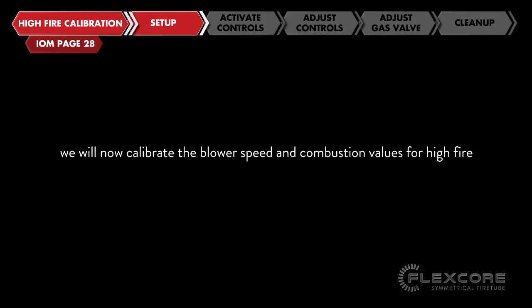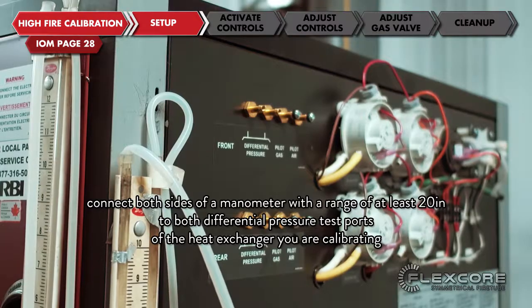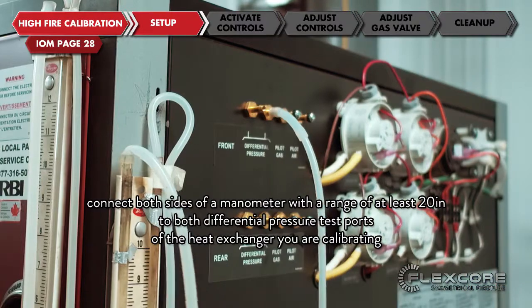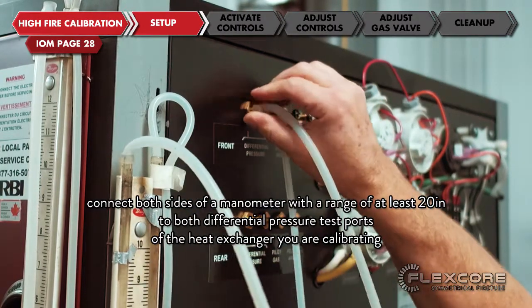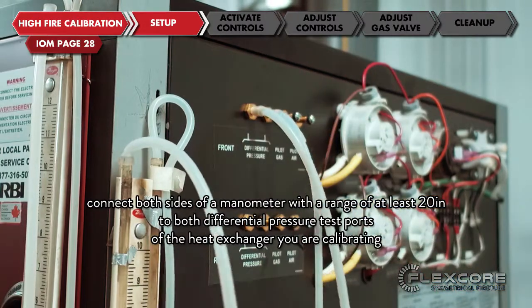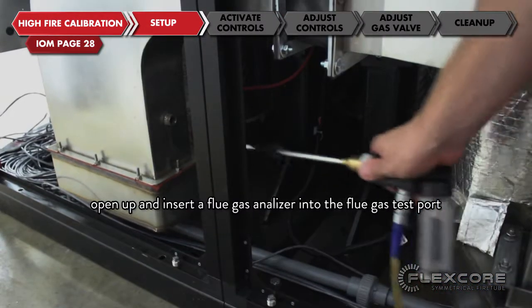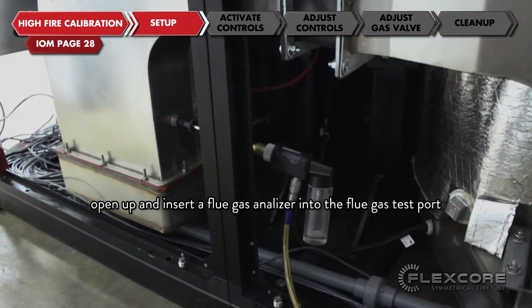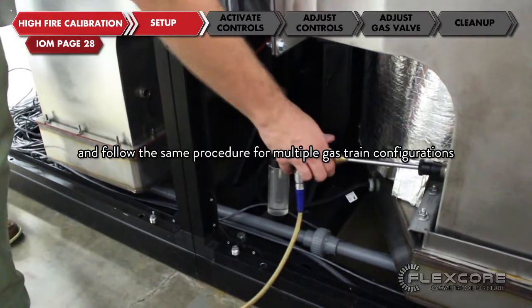We will now calibrate the blower speed and combustion values for high fire. Connect both sides of a manometer with a range of at least 20 inches to both differential pressure test ports of the heat exchanger you are calibrating. Open up and insert a flue gas analyzer into the flue gas test port, and follow the same procedure for multiple gas train configurations.